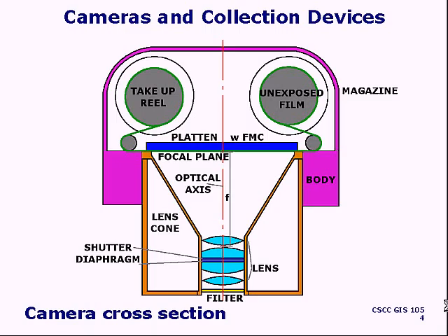There's going to be a filter that is going to account for things like reducing haze, uniformly distributing light, and protecting the lens. Usually for black and white photography, as we mentioned before, a yellow filter is going to be used to cut down on the haze, to cut down on some of that refracted blue light. So that is what a typical aerial photogrammetric camera is comprised of.